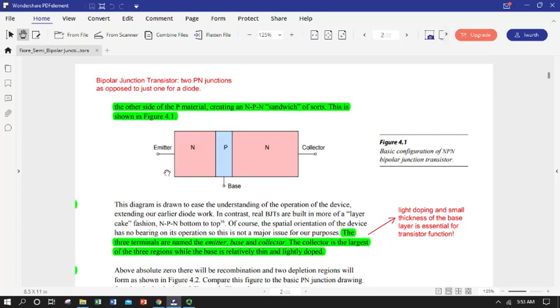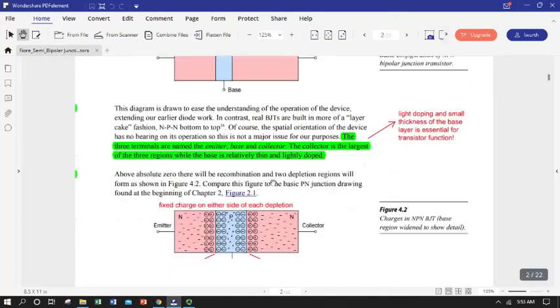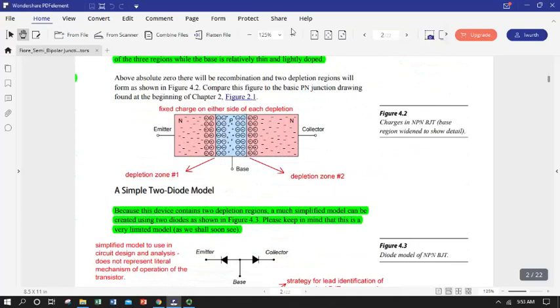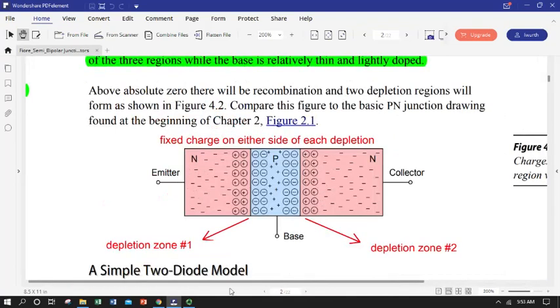Okay, so emitter lead. We have one type of semiconducting material, reasonably thick, reasonably heavily doped. We've got our base, which is the opposite of whatever the emitter and collector are, thin, lightly doped, and the collector fairly large, very heavily doped in the same type of dopant that the emitter was. Okay, emitter, collector, base.